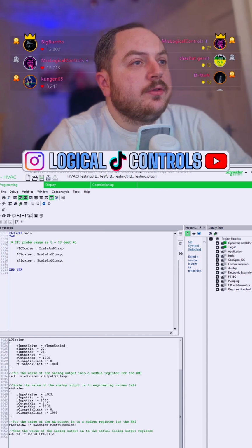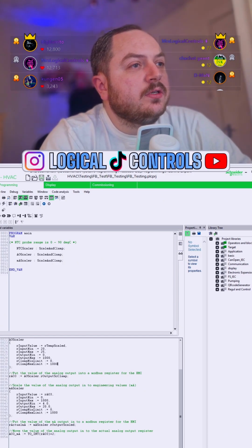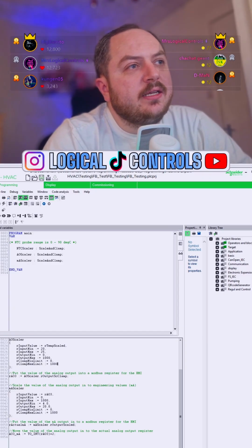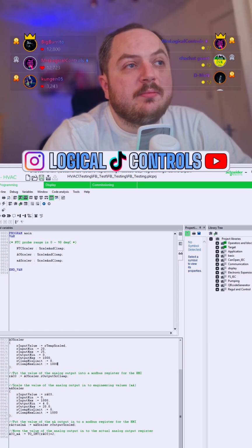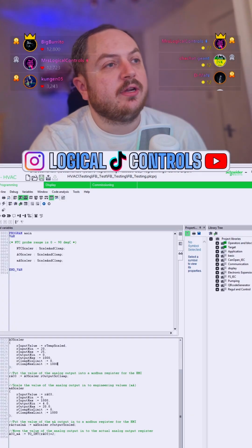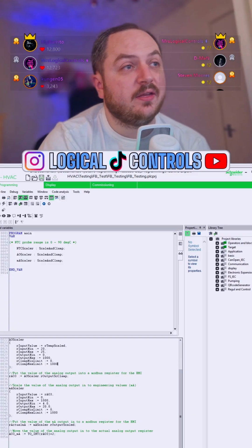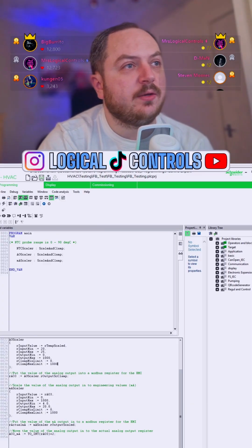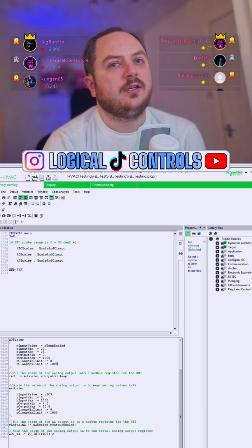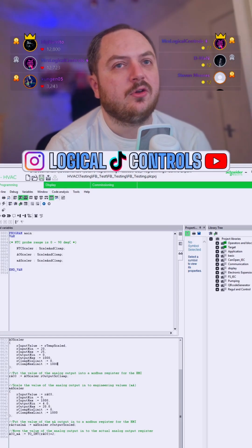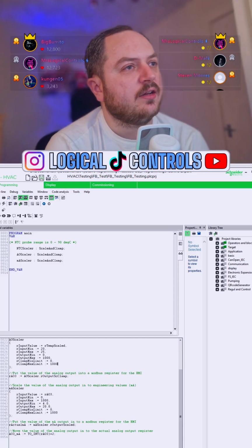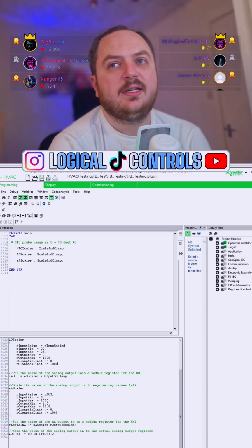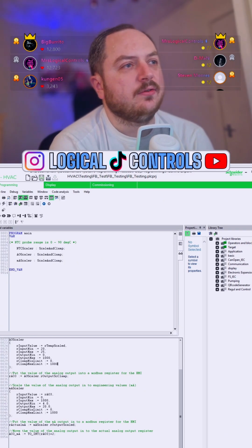For control panel use, think BMS link via BACnet instead of volt-free signals. Yeah, I've found that to be dependent, really, David. I know BACnet is used in BMS a lot, but the majority of the time when I've had to interface with a BMS, they've usually asked for Modbus registers. With the odd occasion where they want volt-free stuff. Normally for the important stuff, common shutdown, common fault or something, they want that on a volt-free contact. But then they'll pick up the random power data and stuff like that over Modbus.